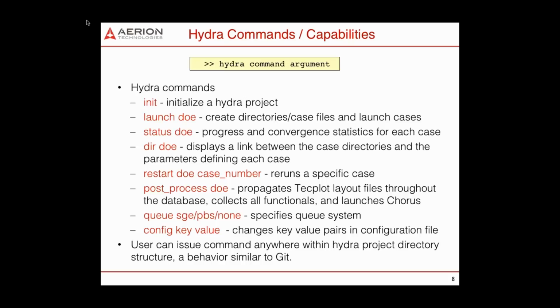The post-process command allows people to propagate Tecplot layout files, collect data, and automatically launch Chorus at the end of that. Like I said, there's an interface with the SGE and PBS systems, so one can specify the queue system ultimately to run on, or if you specify none, to run on localhost. And there's also some configuration associated with Hydra to allow a customization of commands, and so there's some config options as well that are supported.